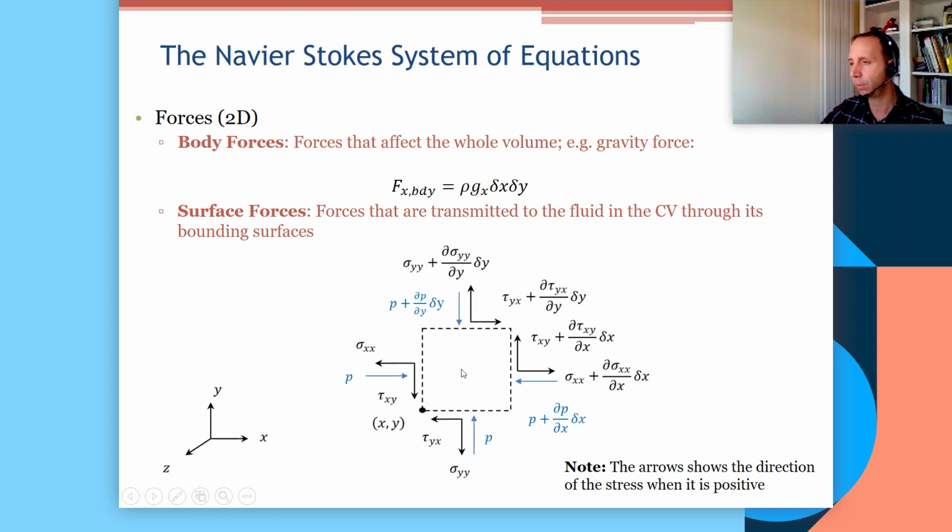What matters when it comes to the force acting on the fluid inside is the balance between all of these. So if we imagine that the only stresses that are important are this one and this one, let's assume the rest is not important. You focus on that and that. The force due to a stress is the stress multiplied by the area. So you multiply that stress here by the area there, and that stress by the area there, and you look at the balance. This one pulls to the right, this one pulls to the left.